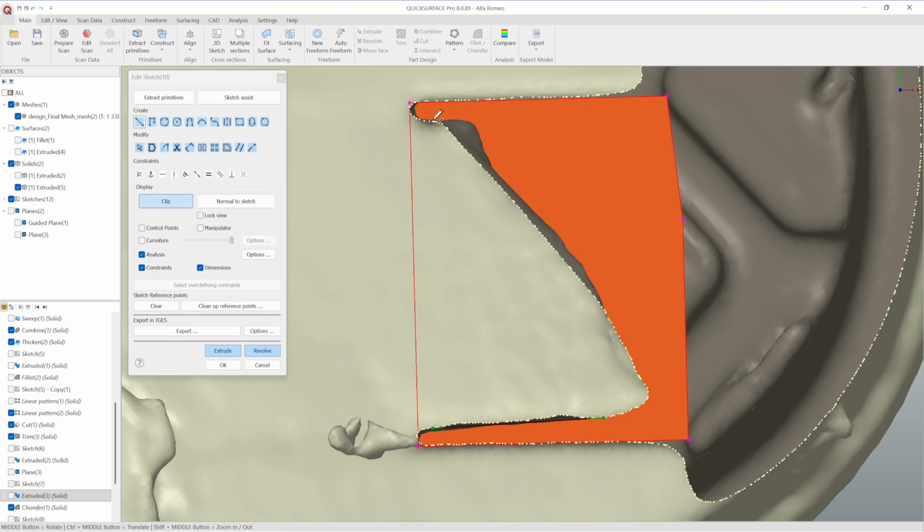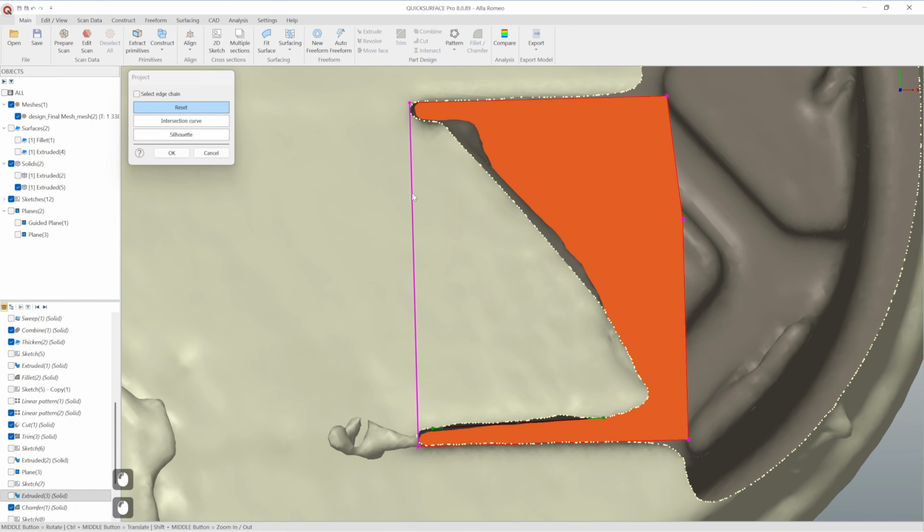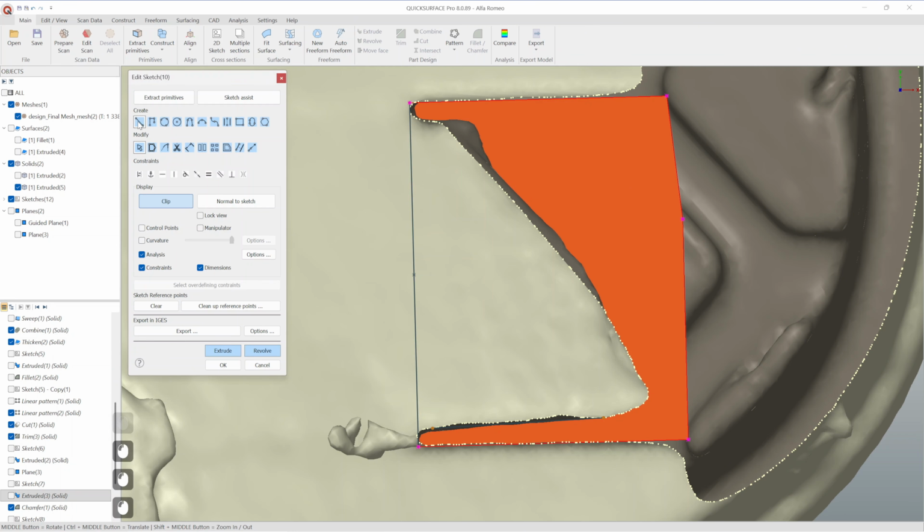And in order to recreate the same on the opposite side, I can convert this edge to a line. Let's create a middle line here. Say this is for construction, this one as well. I'm going to select this entity, construction line, and say mirror. So both of them are at the same angle.